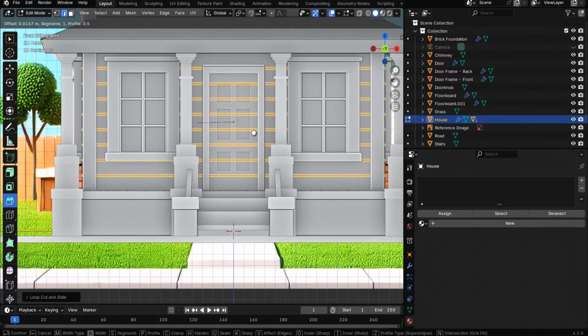So this is a way that you can make your geometry look even more stylized, because you can make it kind of bend and loop and curl, and now you can rid yourself of that kind of Frank Lloyd Wright perfectionist vibe. So if you're doing anything that's stylized, the lattice modifier is just an absolute prairie home companion.